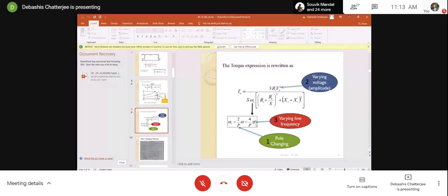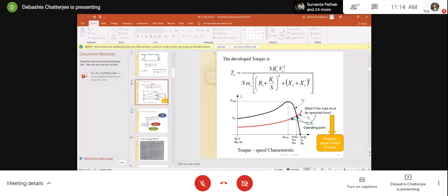So why is this torque relation there? If you see the previous slide that I showed, when you try to vary the speed, you vary the torque also. That means you have to see both: how you can vary both torque and speed to shift the motor characteristic to match the new load operating point. Is that clear to you?